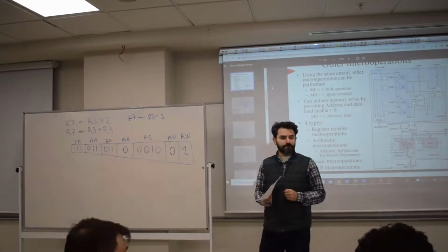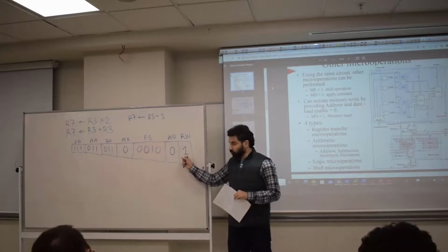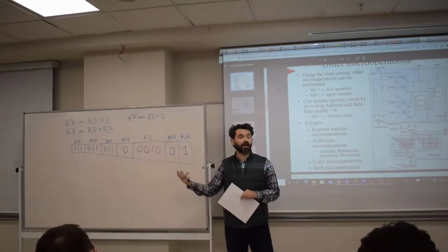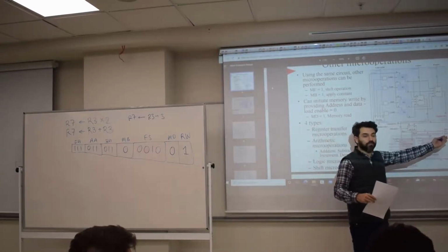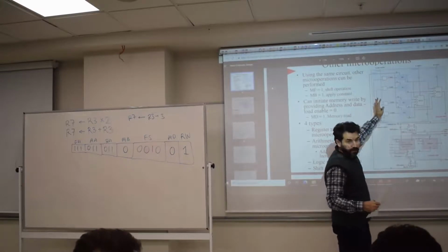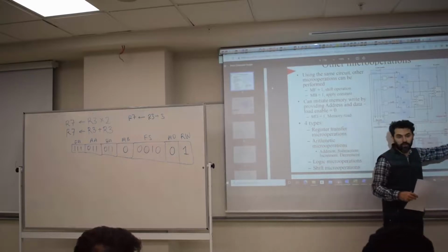What if the read and write is 0? What will happen? You usually have a 1 here, because you usually write something to the register file. But sometimes you don't have to. For instance, if you would like to write something to the memory, then you use these 2 buses, right? You've got nothing to do with the rest of the circuit, nothing to do with the register file. You read something from the register and you write it to the memory.